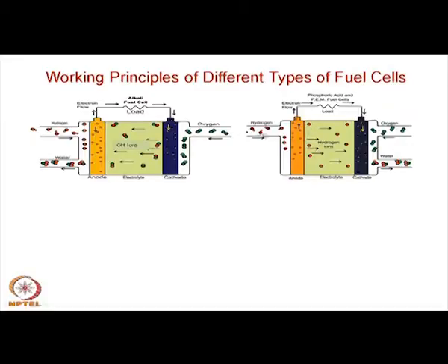And then this is the source of hydrogen, and hydrogen gets ionized there and becomes hydrogen ion. It moves in this direction, combines with the oxygen on this side, and takes up the electron from there. The electron moves in the outer circuit and the hydrogen ion moves in the internal circuit. So internally the charge carrier is hydrogen, and externally of course there is an electron flow.